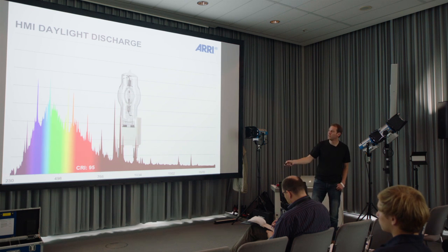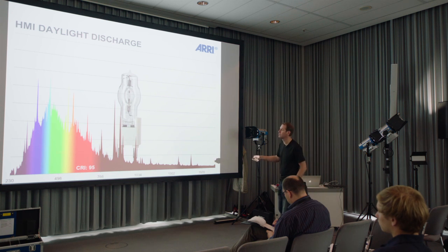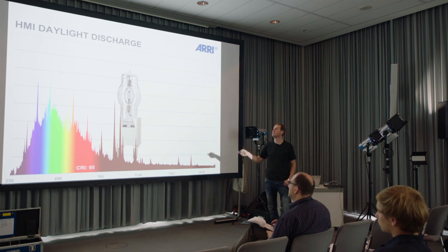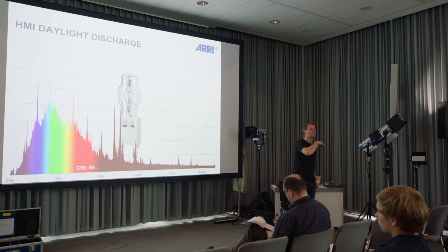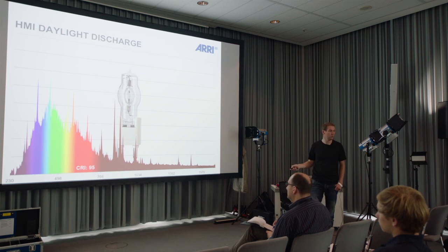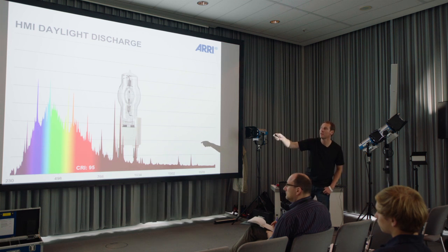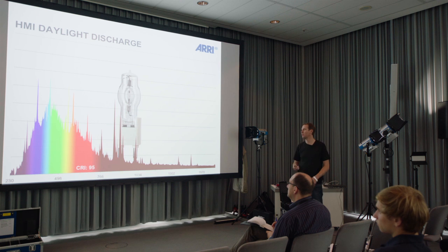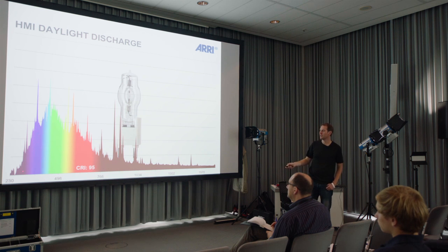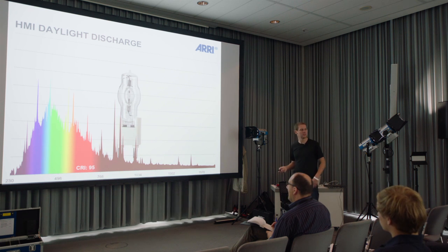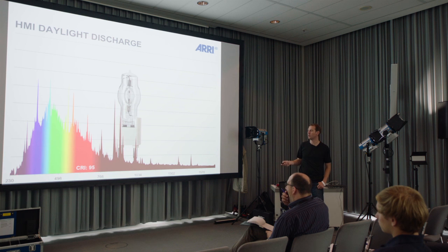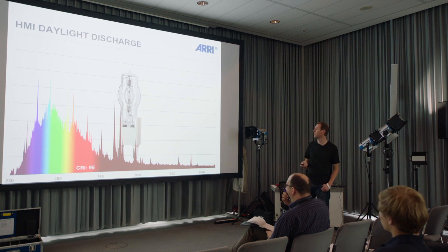And also important, this part, like here, dark purple, this is UV. Very important to know, HMI produces also UV, dangerous UV. So it's very important that all the fixtures, we have the HMIs over there, all have a protection class, UV protection. Because this is not the nice UV that gets you brown skin, it's really dangerous. So we have to use protection glass.